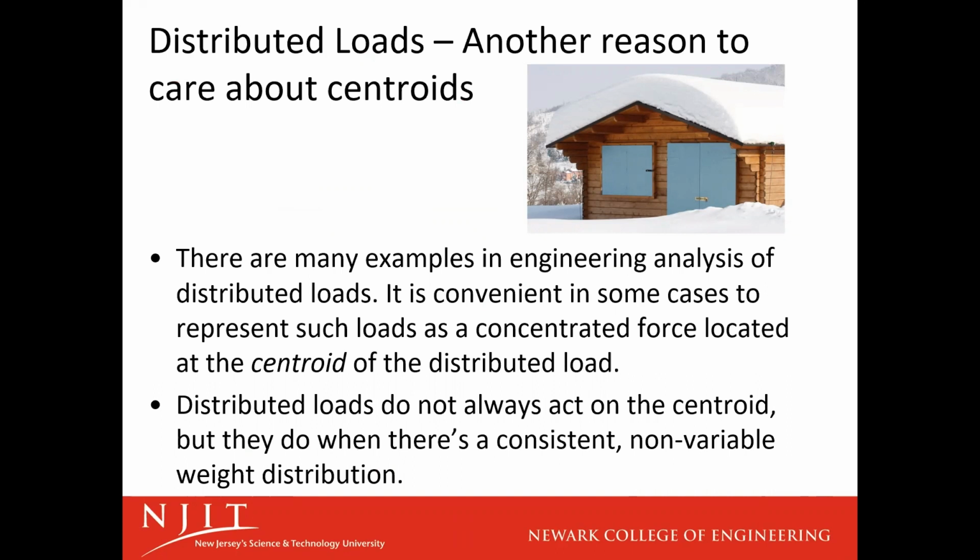Weight can definitely be distributed over an area, so over a surface area or over a set volume. What ends up happening is it becomes convenient to represent the load. So for this distributed load, we figure out its point force equivalent. A point force is like if you were to have a rope tied to something and you were to pull it, and it's only acting on one single point. It's what we've been working with up to this point, our point forces.